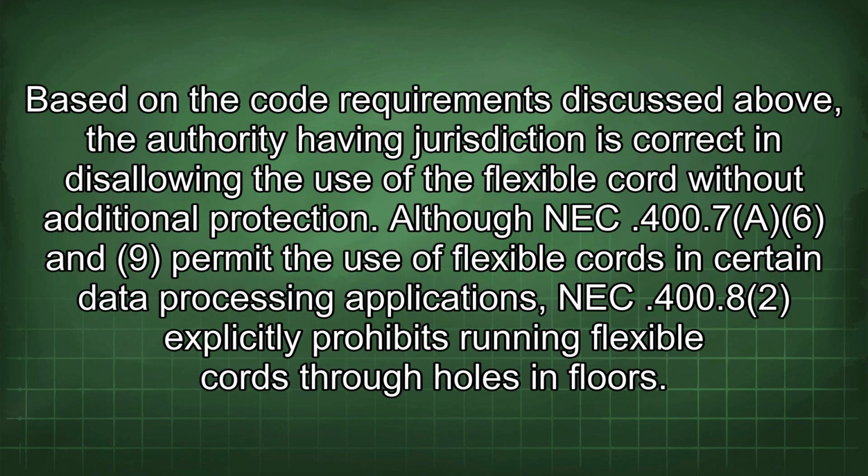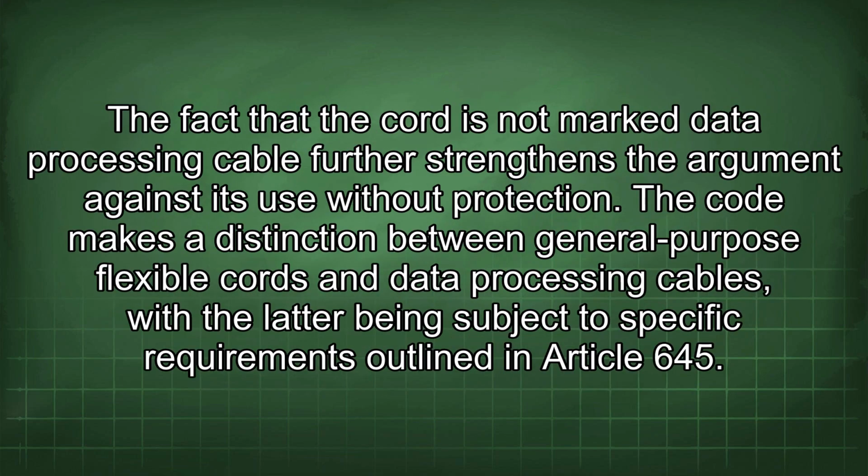floors. Based on the code requirements discussed above, the authority having jurisdiction is correct in disallowing the use of the flexible cord without additional protection. Although NEC 400.7 and 400.9 permit the use of flexible cords in certain data processing applications, NEC 400.8 explicitly prohibits running flexible cords through holes in floors. The fact that the cord is not marked data processing cable further strengthens the argument against its use without protection.